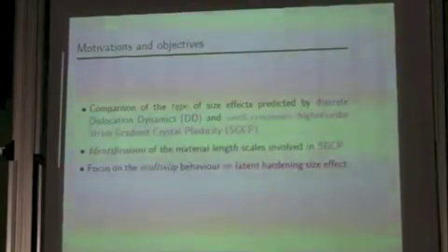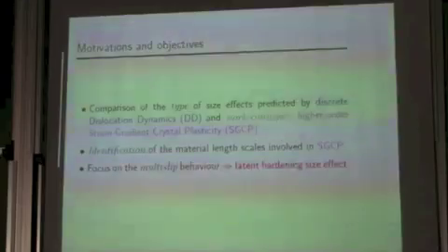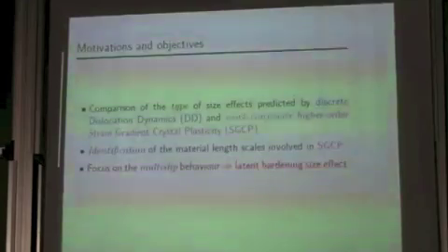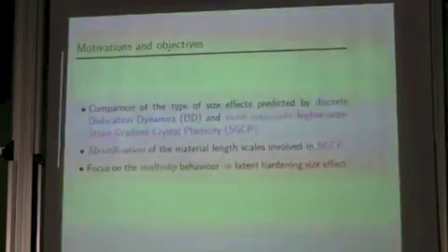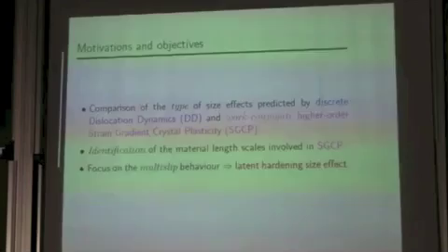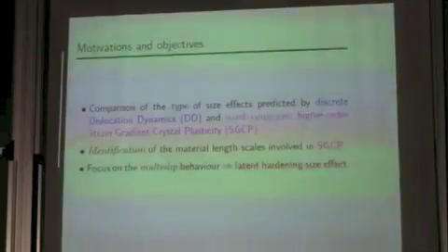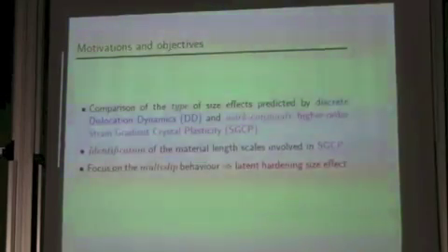So the motivation for this work was just to try to compare the results of strain gradient crystal plasticity with those of discrete dislocation dynamic simulations. We wanted to use the latter as pseudo-experimental results to identify the length scales involved in strain gradient plasticity. Actually, it turned out to be quite a difficult task because we found out some effect, which is the main title of this presentation: this huge latent hardening size effect.